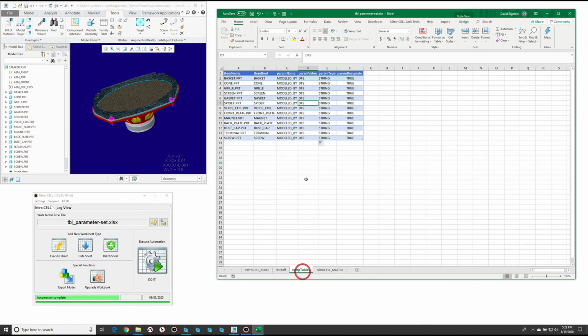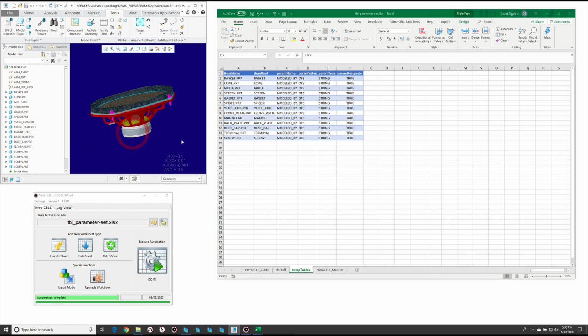And the other big advantage of using a table like this is that you can actually use them on the outside of or the output of a Power Query process. So if you have changes that you're trying to make, it's sometimes very easy to pull data out of Creo, run them through Power Query, make the updates and changes that you need to transform the data, and then get a table back out, and then just reference that table as something that needs to be populated back in. And it's pretty straightforward.